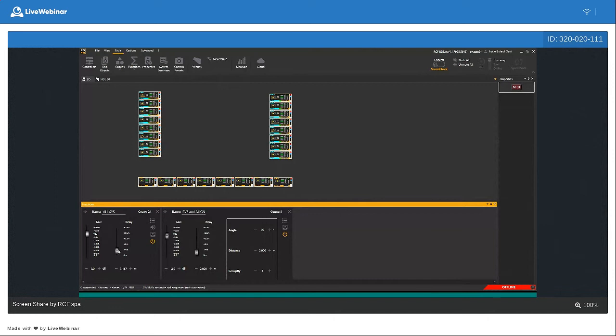I can move it back, for example in a theater, to align the system to the drum. And I can also change the overall gain of the system, according to the level that we set before between tops and subs. This is another gain after everything, which keeps all the differences between levels, alignment and so on, managing the global amount of gain and the global amount of delay.